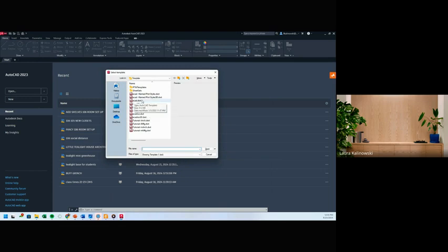And we're going to start with AutoCAD.dwt. Yours might just say AutoCAD. Avoid any of these other ones where it says named plot styles, AutoCAD, ISO. We're not going to be using those right at this time. Just plain AutoCAD.dwt.